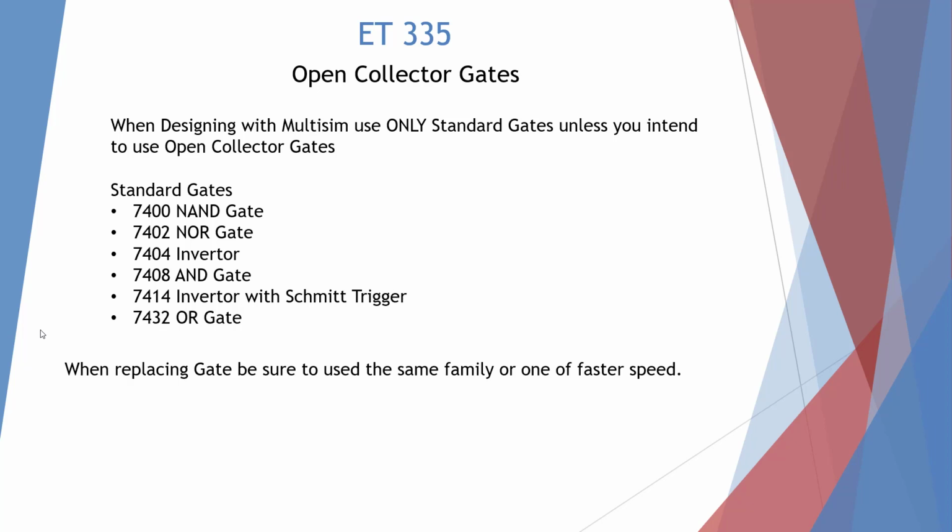Whenever we're designing with Multisim, we should use only standard gates unless you intend to use an open collector gate. This is a common mistake students make, grabbing the wrong type of NAND gate. So if it is an open collector, it will not go high unless we put an external pull-up resistor, and the logic's not going to work.